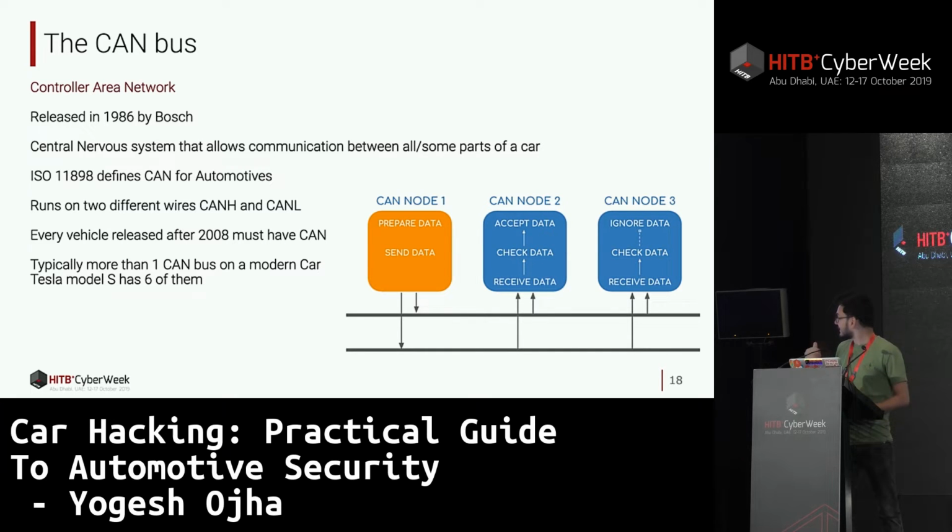So this is when the boss came up with the idea of CAN bus, where you can just have 2 wires, CAN high and CAN low, and all the components are going to get connected to each other using just these two wires, CAN high and CAN low. So it integrates all of these complex components in such an elegant way that all of these components can interact with each other at a very fast data rate.